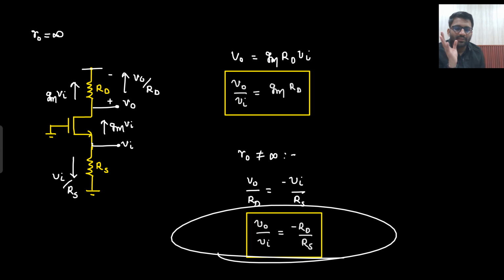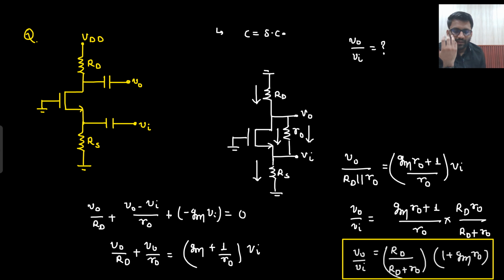There is nothing wrong with the small signal analysis, but if I see as an engineer, this gain is independent of anything, like it is not even depending on any circuit parameter. It is not even depending on GM. It is just depending on the two resistances that the user is connecting, RD and RS, or it is coming from any other stage. So how is this common gate circuit helpful then? It is independent of GM value. Okay, I will think about it, but for this video,